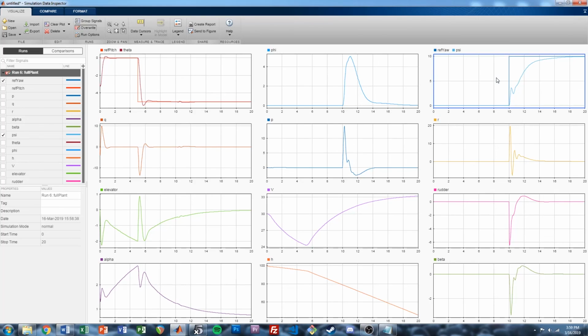So I think this looks pretty good for now. You can always continue to play with it and do some sensitivity analyses to see if you're flying at different velocities, or you have smaller or larger changes. Maybe you have a coupled response in pitch and yaw. See what the responses look like there, and then you might need to adjust the gains as well.